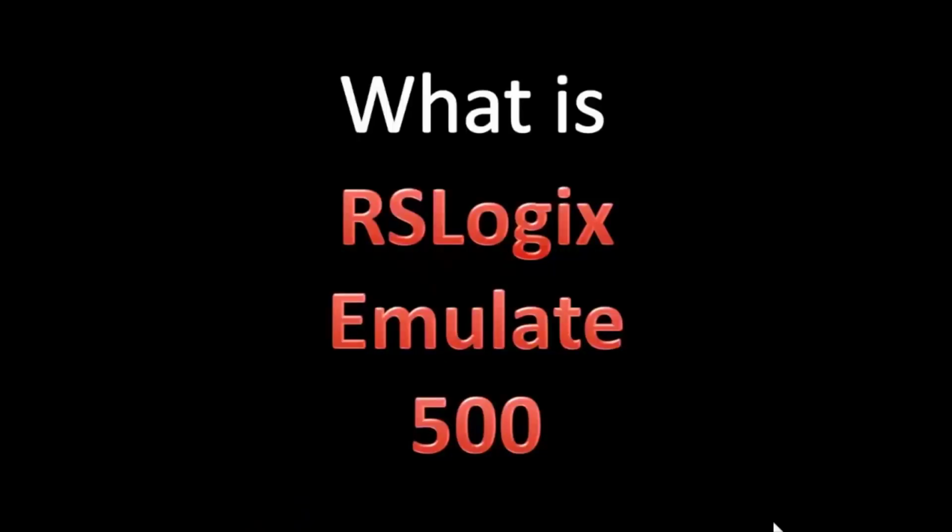The big question is, what is RSLogix Emulate 500? There are three pieces of software needed to create this simulator. You need RSLogix Micro Lite, that's the programming software, and then you need something to connect it to a PLC, or in this case to the Emulate software, and that software is called RSLinx. So RSLogix Emulate 500 is an application that emulates processors that can be supported or programmed with RSLogix 500. In this case, it's only going to be the MicroLogix 1000 or 1100.